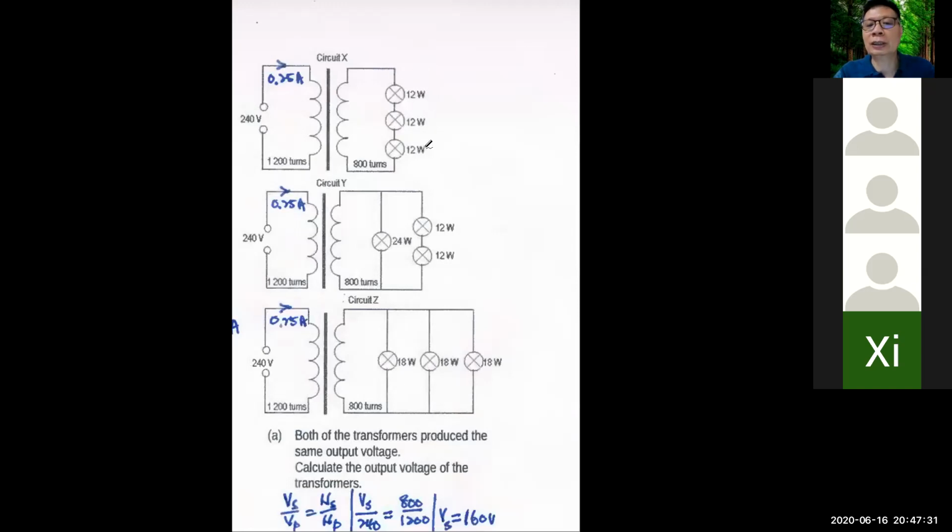You just add up everything. Like this one, you add up everything, so it becomes 36 watt. So input 60, come out here, left 36 watt only. There's a lot of power loss, no good. This one input 60 watt, but output here 24 plus 12 plus 12, so it's 48, slightly better lah. Power goes in, input power 60, output power is 48, not too bad now.